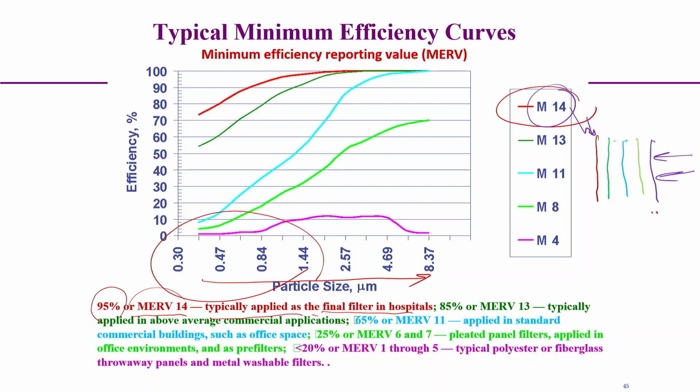Now, during the airflow, by the time it reaches this stage, the airflow rate will be reduced. So, it can capture very, very small particles with an efficiency of more than, say, 75% typically, and for a normal hospital case, we can achieve filtration above 95%.